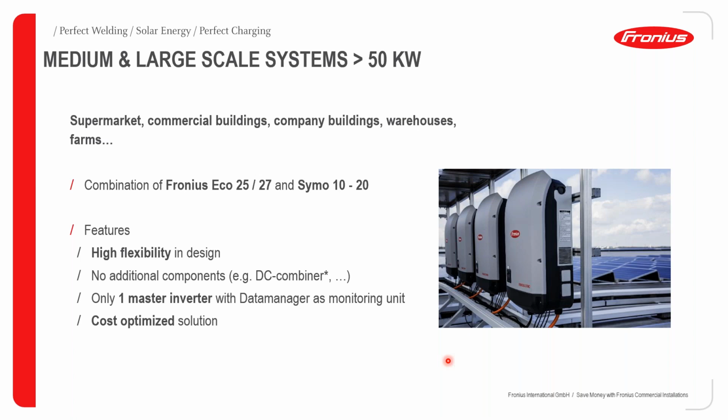One data manager can actually carry up to 100 inverters, but for practical purposes, for ease of communication, and to minimize latency as much as possible, we tend to recommend one data manager per 20 to 25 inverters. So of course, by so doing, this is a very cost optimized solution.